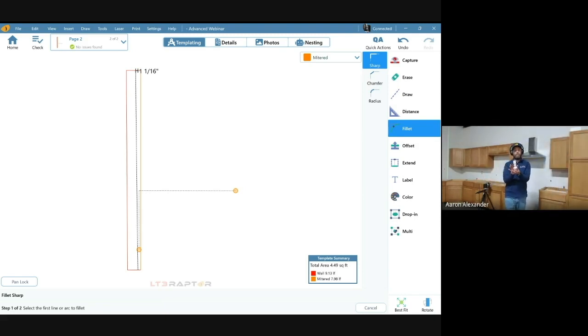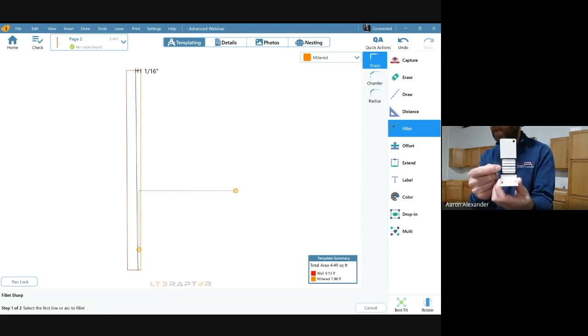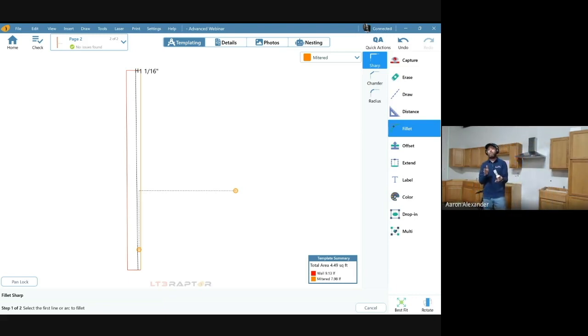It's just an L target with the black channel material from the clamp target, right? We got a sticker on here. That center line, we got a center bold black line, and then those lines are 1/4 inch plus or minus up or down, right? So one thing we could do with this, in my situation here with these uppers, they have a cavity, right? We either are going to have cabinets that have a cavity, you know, it goes up 3/4 of an inch, 1/2 inch off the bottom here. And then there's also the cabinets without the cavity where it's totally flush across the bottom here, flat panel, right? Those are kind of the 2 different styles we're going to run across out there in the field.